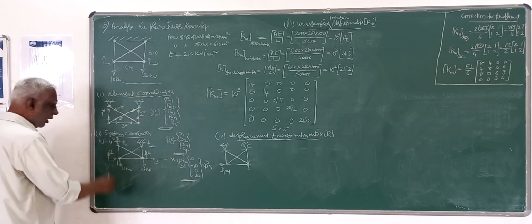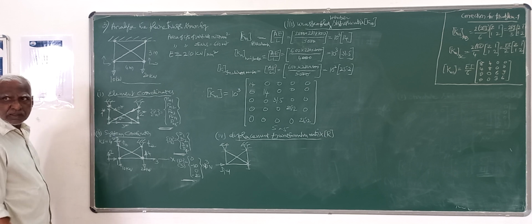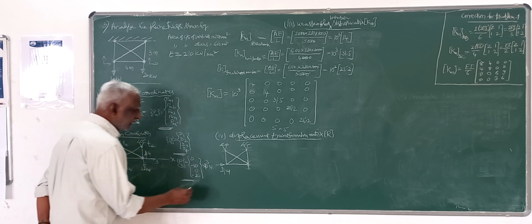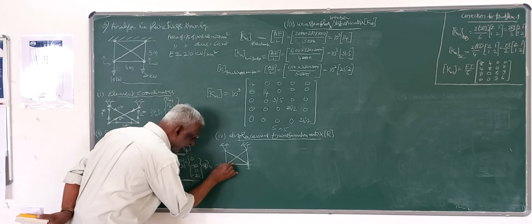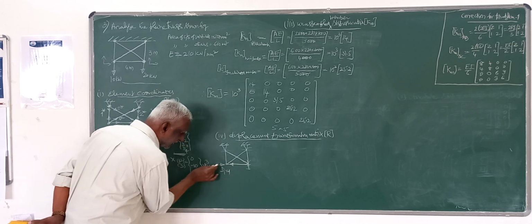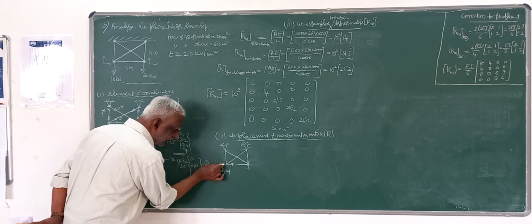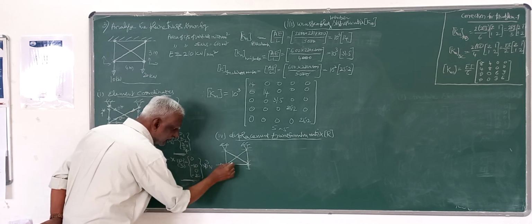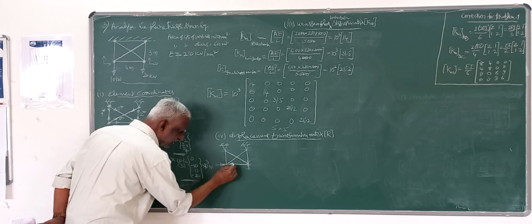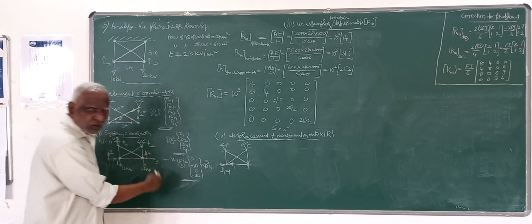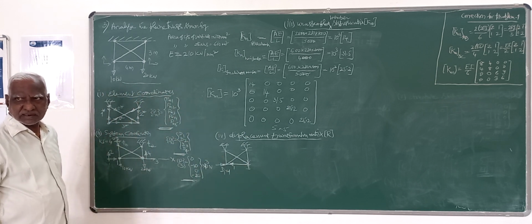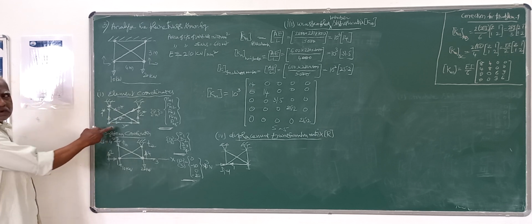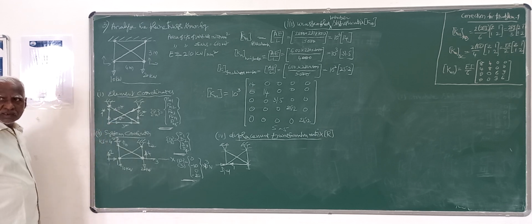So I have to make all vertical displacements 0. Then I will get a displacement in this member, and this should be opposed, so there must be a force here equal to 1 in the opposite direction, that is -1, the force in the direction of 3 in the opposite direction.